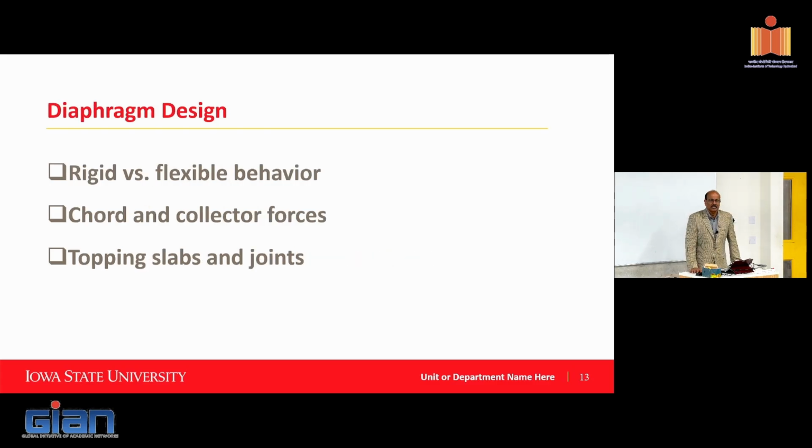One of the most challenging things with precast structures is how you work your floor system into it, right? The floor system is a challenging piece because you're building this from pieces, but they have to act as a continuous diaphragm, so that they transfer the load across.